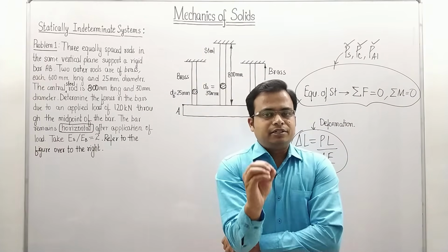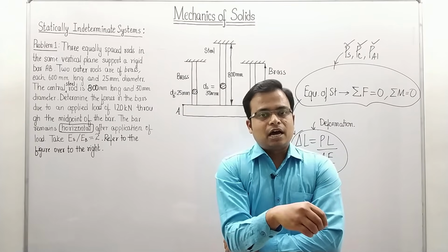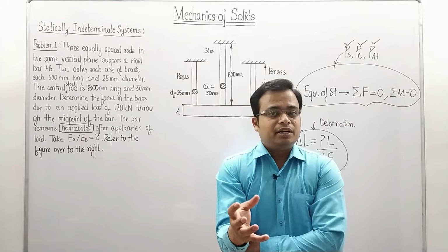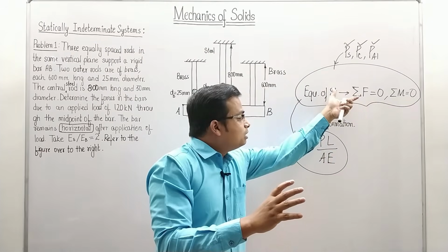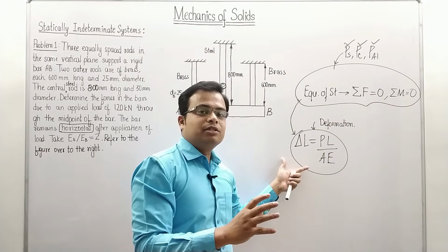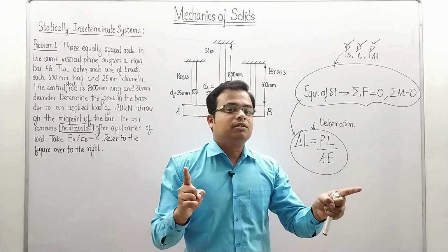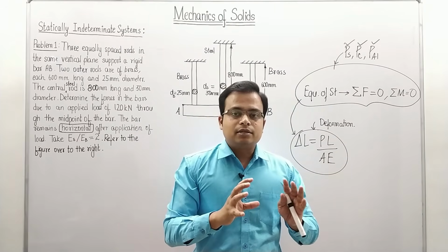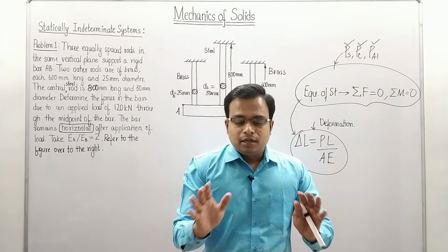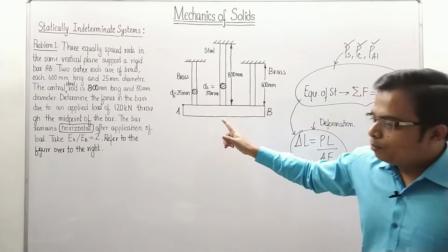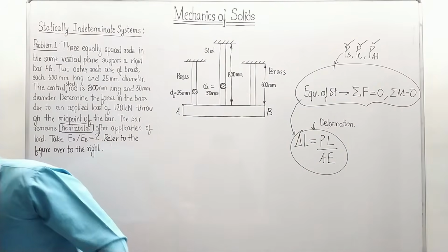Now remember this in a nutshell. If there is a system having 2 or more members having different materials, using equations of statics alone is not enough. It has to be supplemented with equations which connect load with the deformations. Such systems are known as statically indeterminate systems. That's it. Now in that quest, let us take up this problem and let's see what it has got.